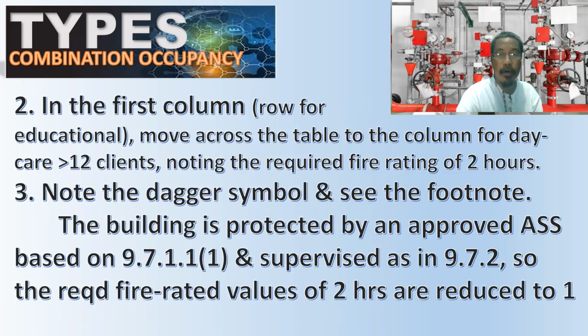Number 2, the first column, row for educational, move across the table to the column for daycare greater than 12 clients, noting the required fire rating of 2 hours.